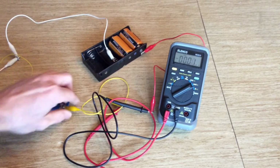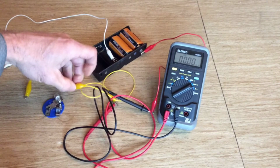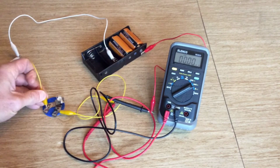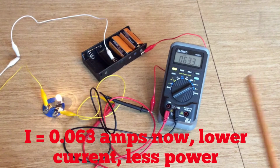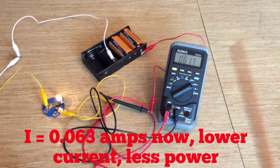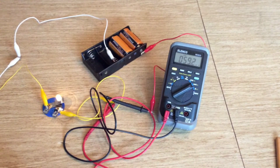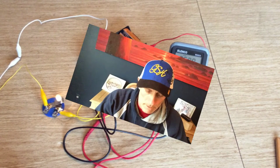Let's confirm that relationship by using the other bulb. I don't know if you can see that. A little bit of difference in brightness, but not as noticeable. And instead of 65, we're down to about 62 milliamps. Now we're going close to about 58 milliamps. So it's definitely a change. Less power, even though the same voltage, because we have less current.